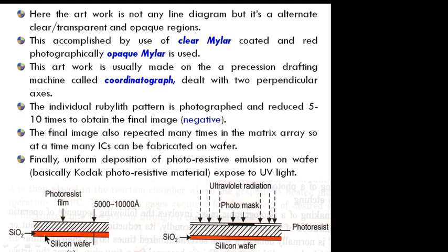This silicon oxide is protecting our silicon wafer, and the photoresistive material's job, as per the mask design, is to give you a chance to etch out different regions of the silicon oxide and remove them as per your need. You can create islands on a wafer, and each island will be used to fabricate a different component, and these components will be further interlinked.